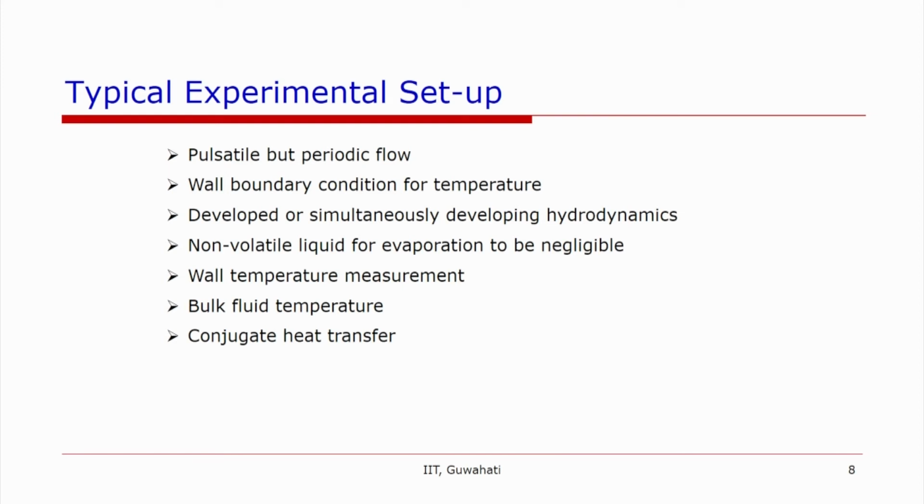So, coming to heat transfer in the Taylor flow regime, the flow in the Taylor flow regime is pulsatile. So, the flow changes with time, but it is periodic. So, it repeats itself after a certain time, or you can see this periodicity in space as well. So, if you are standing at one place, you will see one bubble coming along, and then one slug comes in, and then you have another bubble coming along, and this will be periodic. So, if you are staying at one place, you can see the volume fraction varying with respect to time, and this variation will be periodic.